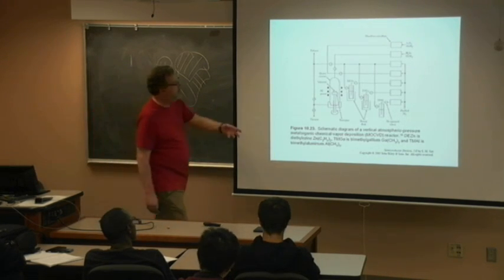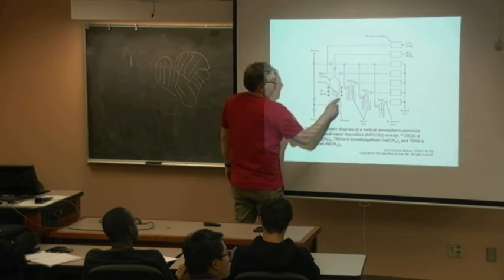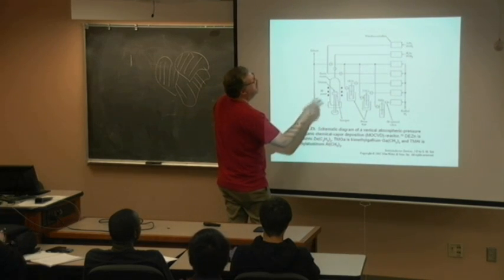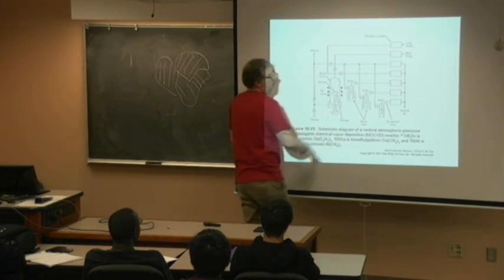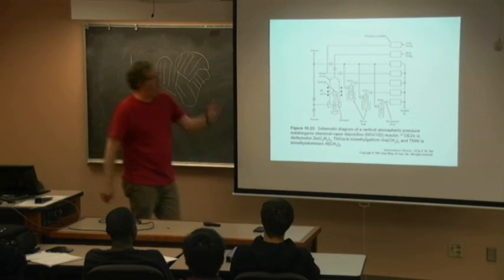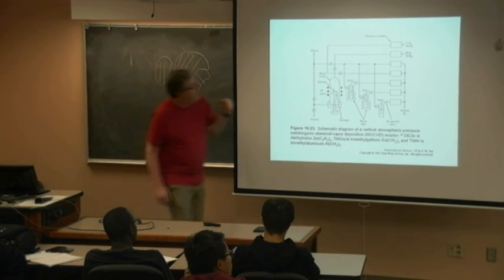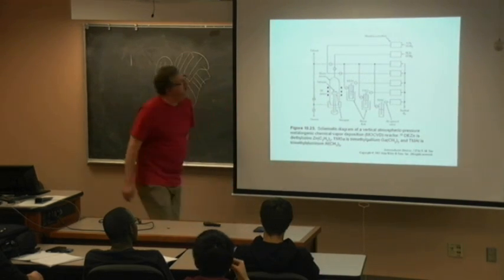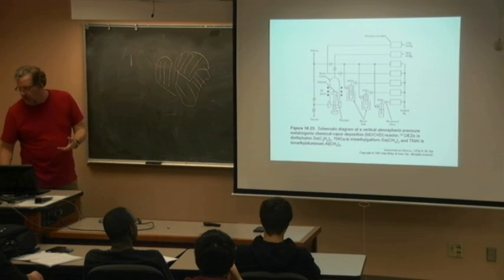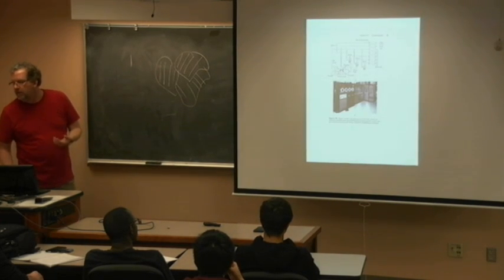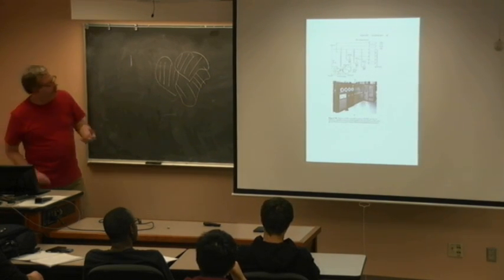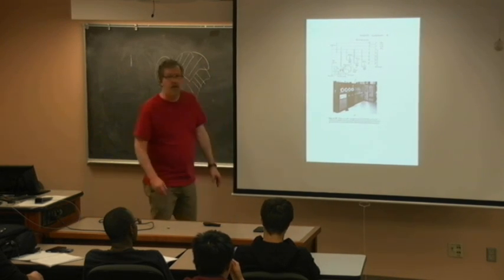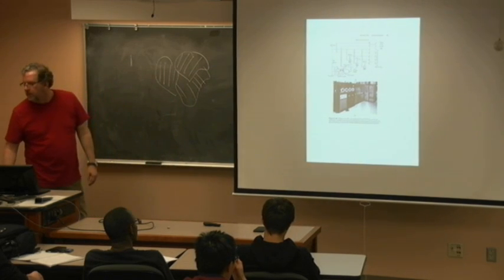Here's a more elaborate one. So it's got gallium, aluminum, zinc as a dopant, arsenic up here. So this is a reactor growing gallium arsenide, aluminum gallium arsenide. And it looks like that's the p-type dopant, and that's probably the n-type dopant. So I can make p-n junction GaAs/AlGaAs structures with that reactor. So here you see, it's just a plumbing nightmare. This is an MOCVD. We have one of these on West Campus, on Kinnear Road, the Nanotech West.